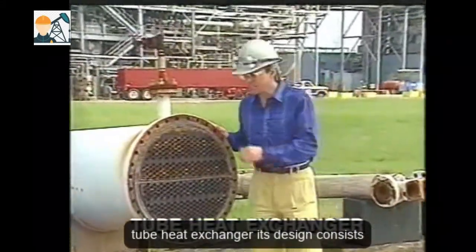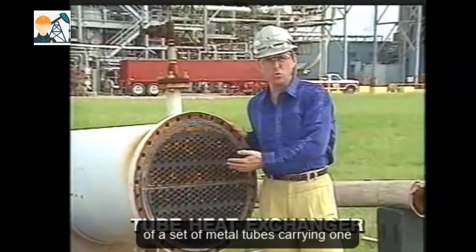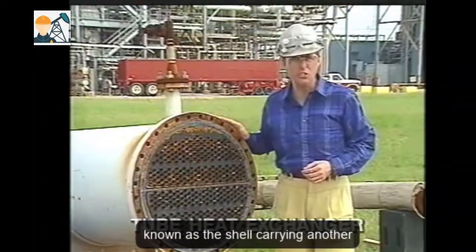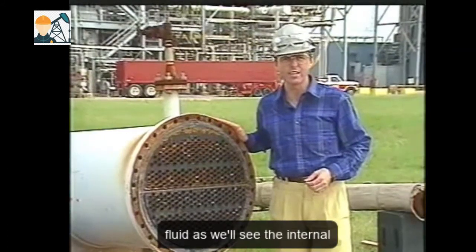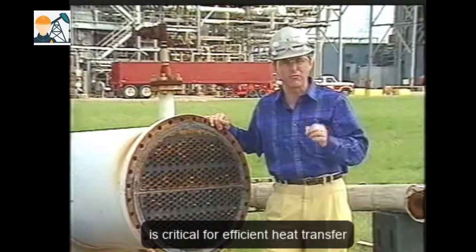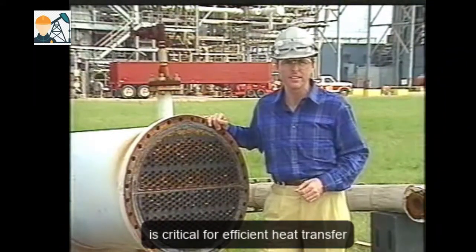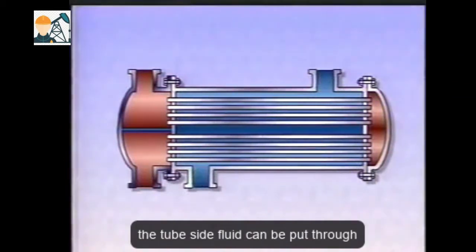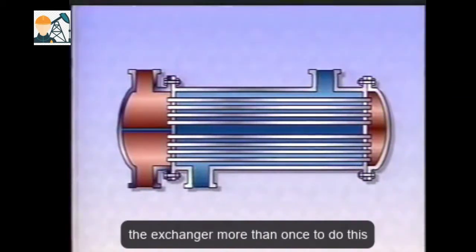Its design consists of a set of metal tubes carrying one fluid and the space around those tubes, known as the shell, carrying another fluid. As we'll see, the internal arrangement of the tube heat exchanger is critical for efficient heat transfer. To increase the amount of heat transfer, the tube side fluid can be put through the exchanger more than once.